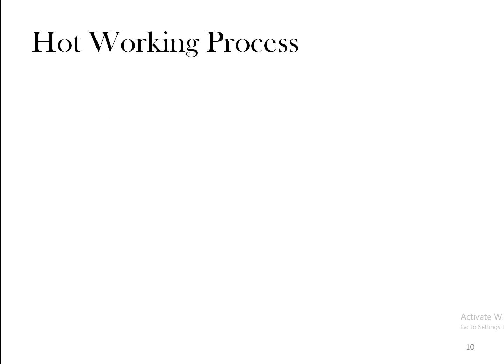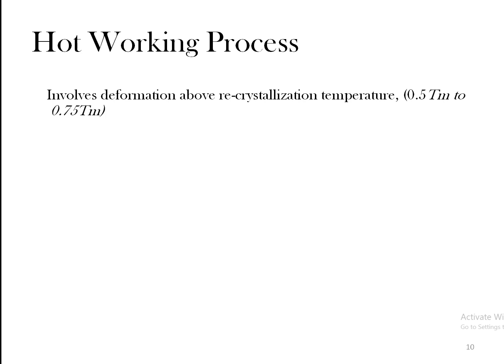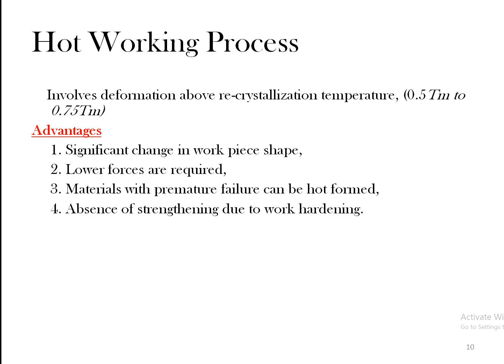Now, coming to the hot working process, the same process is done. The only difference is that the metal is heated above the recrystallization temperature. The basic advantage is that a lower force is required as compared to the cold working process, and materials prone to premature failure can be hot formed. There is also an absence of strengthening due to work hardening.